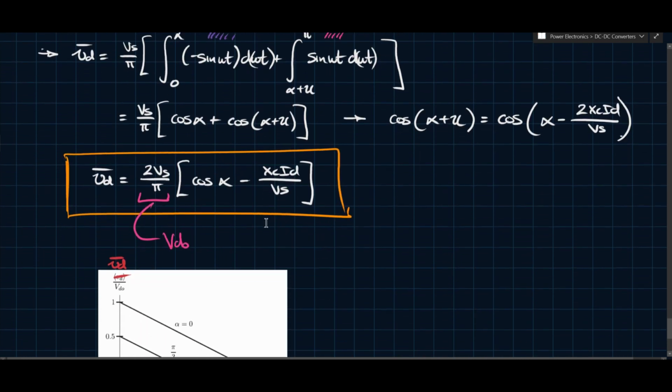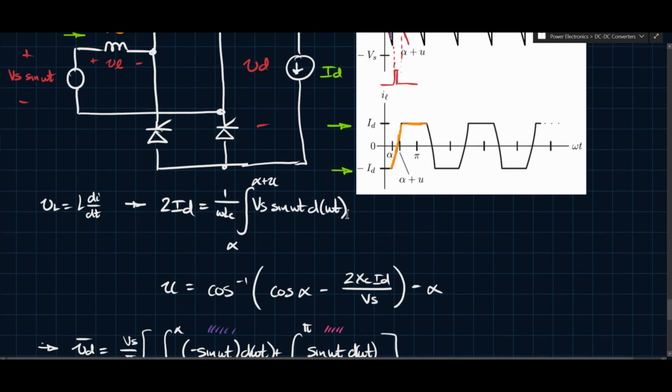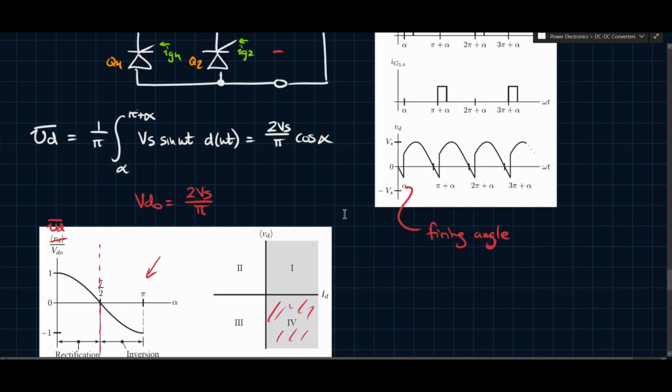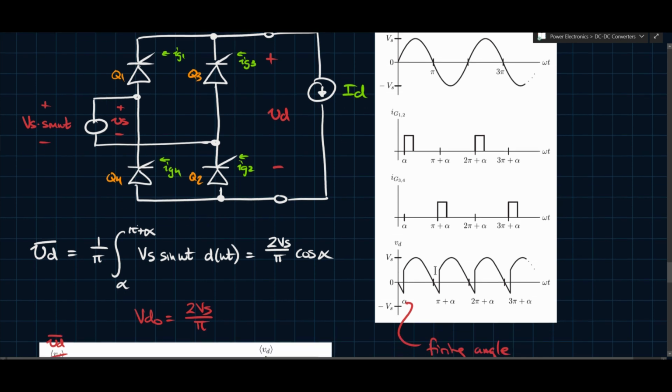But it's a theoretical limit nonetheless, okay? So we looked at here, I mean, we did quite a bit in this video, so let's take a look and recap. We looked at the full bridge, full wave version of the thyristor rectifier here. We saw that we switch in a pairwise manner, as we have previously, and we also saw that this output voltage goes negative, right? Even if momentarily.